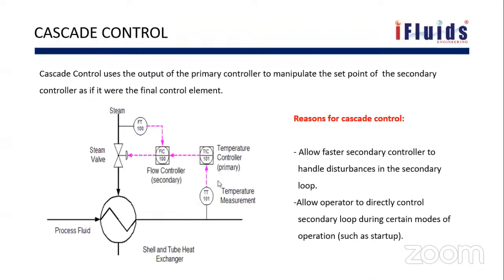And now this is the most important and faster control, cascade control. Cascading is nothing but transferring the effect to the nearby or connected controller. You're cascading the control. What happens here? Two controllers are used, primary and secondary. So we'll discuss with an example.